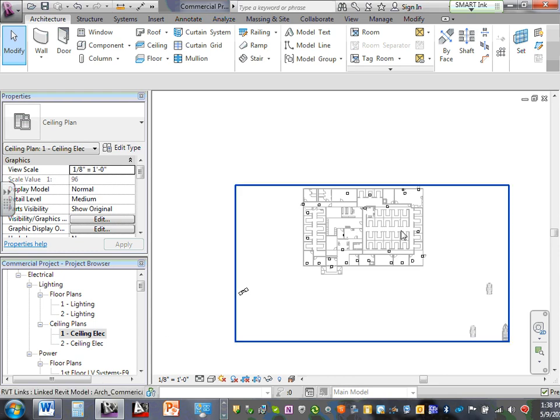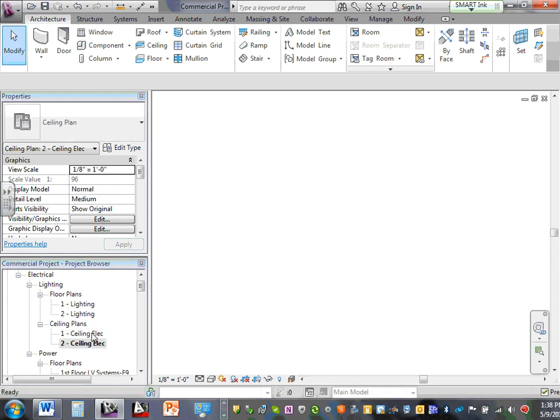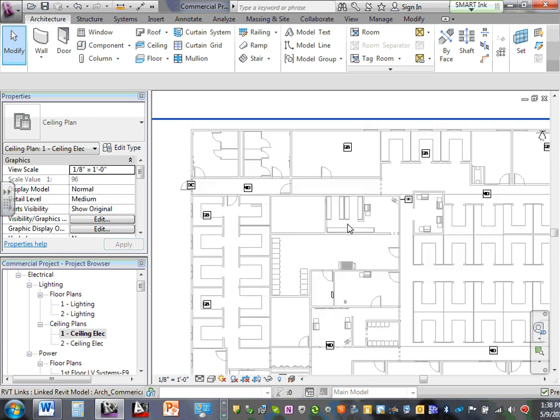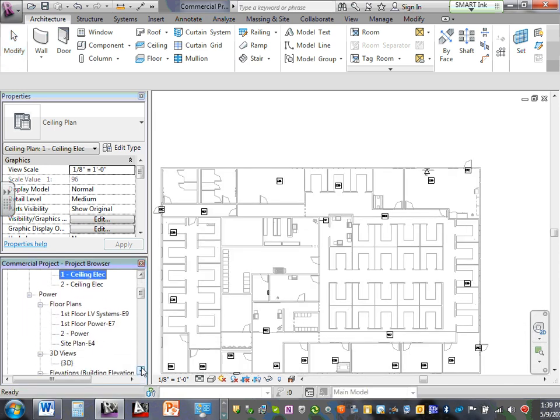If you click on ceiling 1, guys, or ceiling 2, let's talk about ceiling 1. Ceiling 1, everything you drop now, you are in the ceiling. So if you put a fixture, where do you put it? In the ceiling. Okay, so that's the difference between the ceiling and the floor. When it says floor, anything in the wall is considered the floor layout. When you say ceiling, anything in the ceiling, you want to be in the ceiling layout. Ultimately, you're dropping it in the same model. But if you put it in the ceiling, it puts it right here. If you put it in the floor, it puts it right here in this area. It defaults by default.